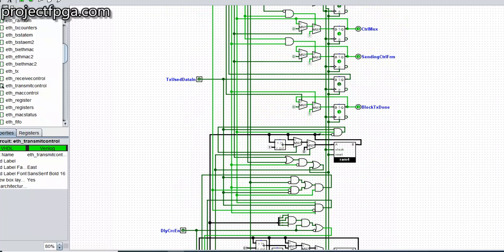But how do we increment it? So this is the incrementer. This here is our adder that increments it by 1. But let's see what does the incrementing. Is it this AND gate here? It is a 3-input AND gate here. So the conditions for incrementing it include, one, let's see, TS used data in. TS used data in, I think we've talked about it.